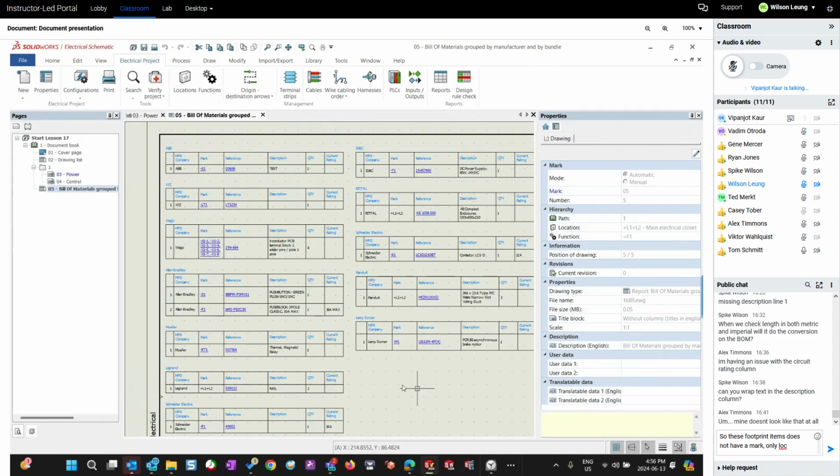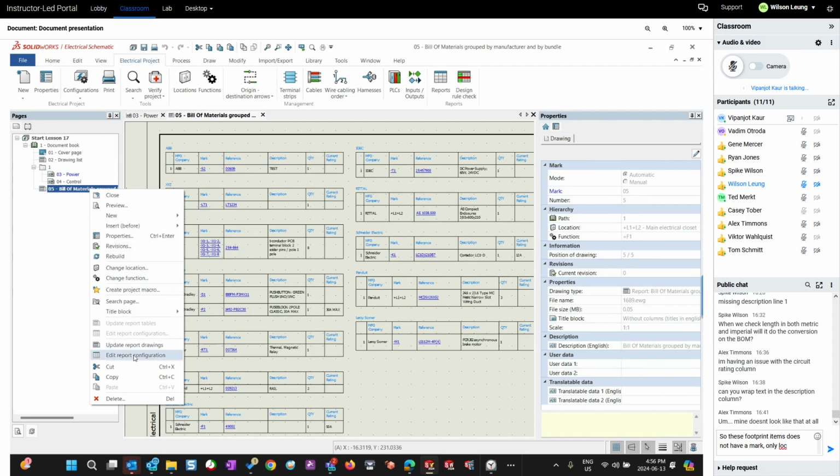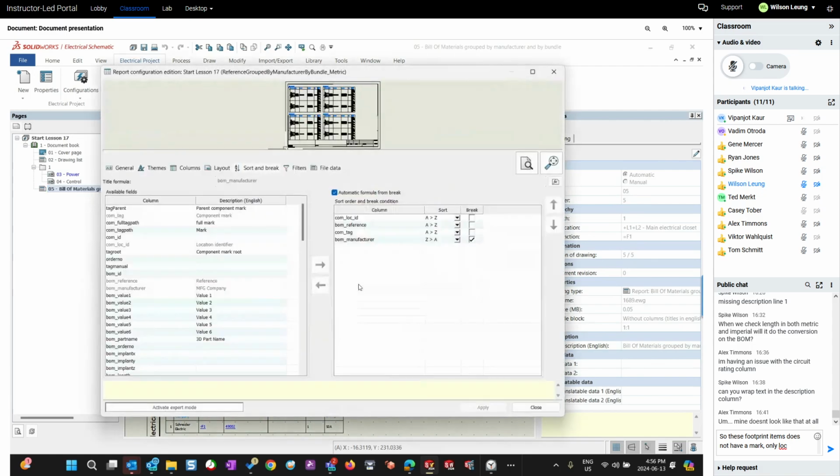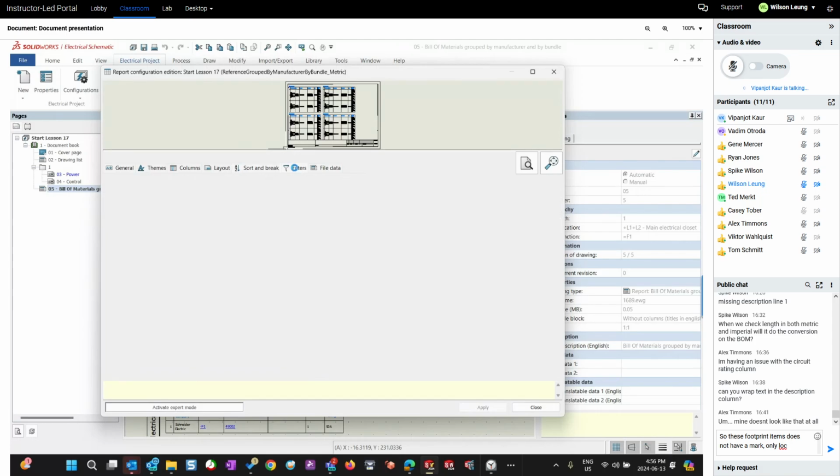Updated. So the very last part, the book doesn't talk about this. A lot of people call us on tech support and ask this. They would say, Vip, I only want to show Schneider Electric parts. Can I apply some filters that only show me that specific item from the report? So if you get back to the edit properties again, one last step is we'll learn to add a filter. So come to your filters tab. Click on this big filter button, please.